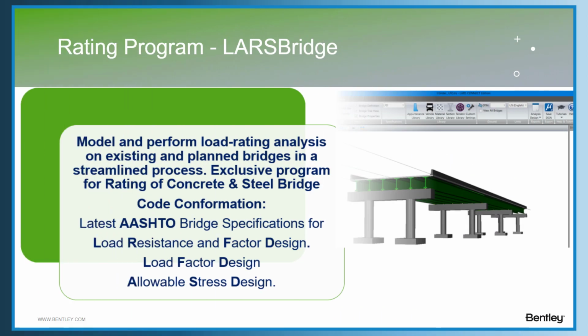So we recently moved from a 2D LARS program to a 3D version of LARS. We call it LARS Bridge, wherein the users can model and perform load rating analysis on existing and planned bridges in a streamlined process. It's an exclusive program for rating of concrete and steel bridges. I would request the users to download it from the Bentley software download website and try to use it. The program can handle AASHTO LRFR code, LFR code, and allowable stress design.